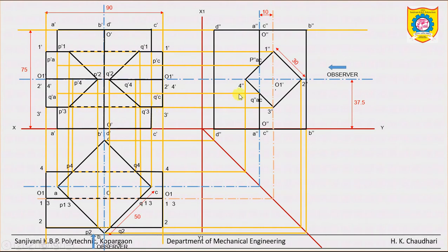Now see the top view or the front side view. See here, from point P1 to this A. Now this A means PA, suppose it is on the back side, because due to this inclined face 1 2, we can't observe this 1 4 surface. So between PA and P1 there is an edge but hidden.